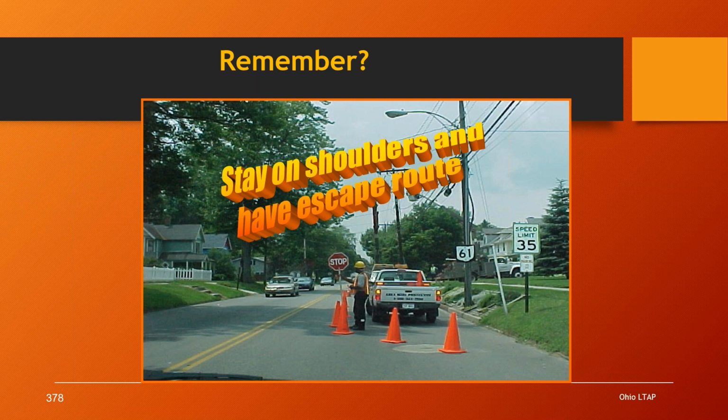So there's a situation where the flagger is standing out there, not on the shoulder of the road, but out towards the middle of the road. We don't really want to see that. So we could have done a better job here of not parking vehicles right here. And this taper isn't right either. We need it to be 50 to 100 feet and go all the way from the shoulder of the road out to the center line, and have at least 6 cones and maximum spacing of 20 feet, as is shown on the table on page 17, the middle table.